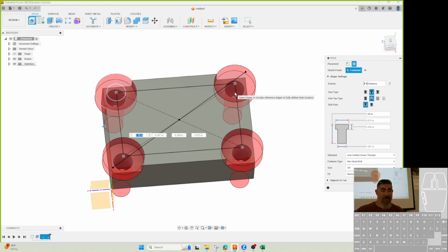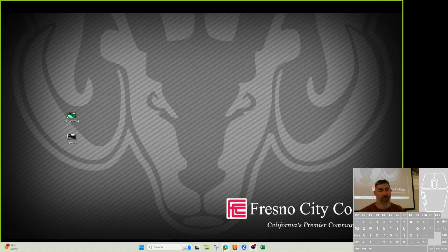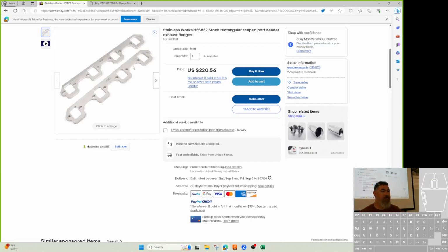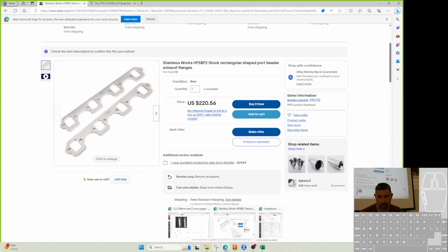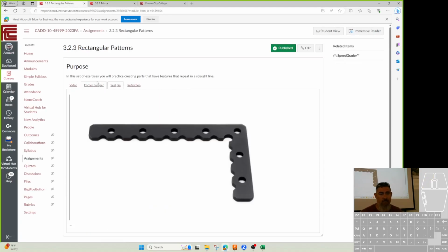So rectangular patterns are used less often, but they are used for things like this, where we need to have a kind of complicated thing bounce over a few times. We put it in like that. Also, the example for this one is another undimensioned one. I guess that's like an inch. But here we can make one hole here, pattern that hole all the way out there, and then make a hole here and pattern it there.